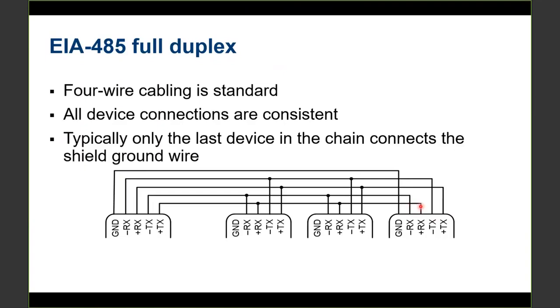and that's why we call it a differential. The mode of communication is a differential, because you're basically able to take the difference between these 2 voltages to recreate your signal. So now think about it. If you have noise introduced on this cable, now the noise will affect the RX minus and RX plus the same, but the difference in those 2 voltages should still be the same, even if they've been offset by some noise. And so that's why this 485 is so resilient.